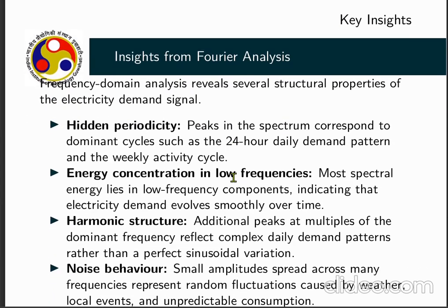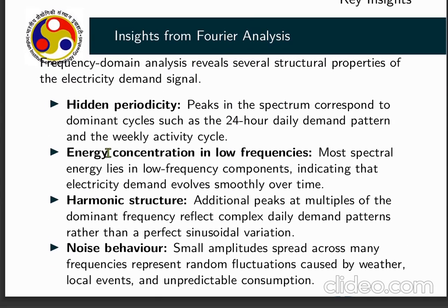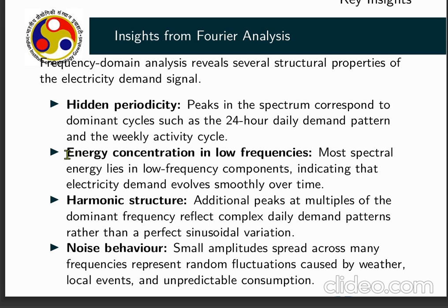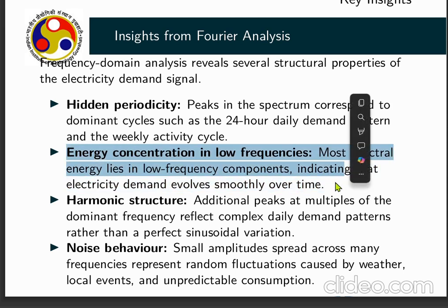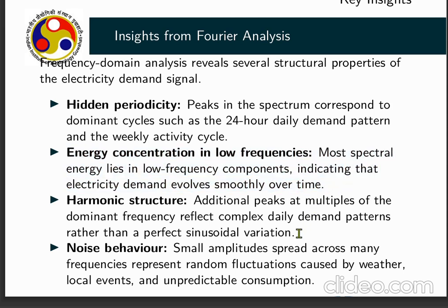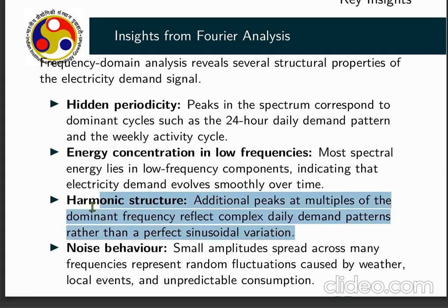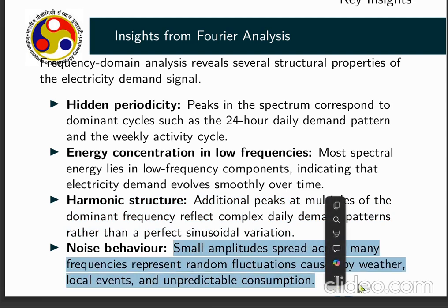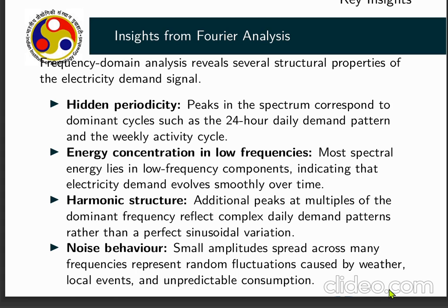Using the analysis above, we can extract several insights. First, Fourier analysis reveals hidden periodicity, particularly the daily and weekly demand cycles. Secondly, the majority of signal energy is concentrated in low frequencies, indicating that electricity demand evolves gradually. Third, the smaller frequency components represent noise and short-term variations caused by weather and other unpredictable factors. Thus, the frequency domain provides a structured interpretation of what initially appears to be a complex signal.